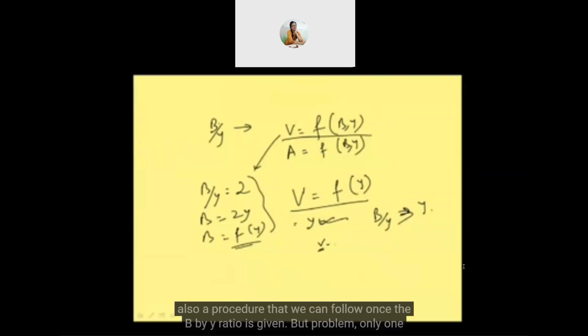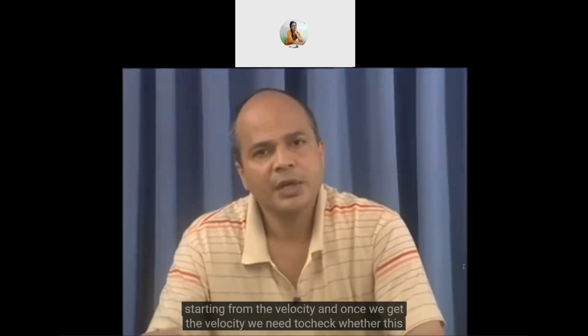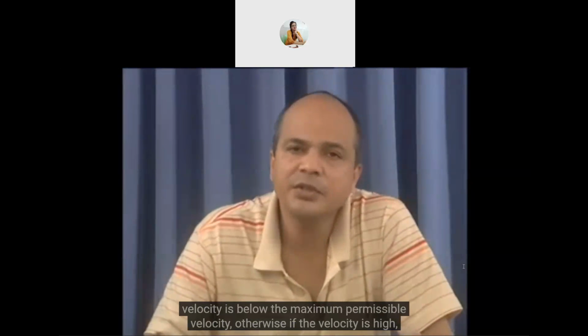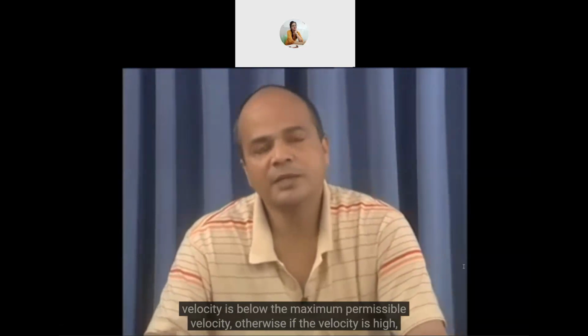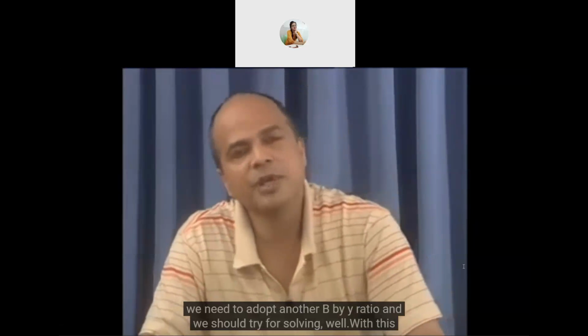But only one problem is that when we are using B by Y ratio, then we are getting the velocity. We are not starting from the velocity. And once we get the velocity, we need to check whether this velocity is below the maximum permissible velocity. Otherwise, if the velocity is high, we need to adopt another B by Y ratio, and we should try solving again.